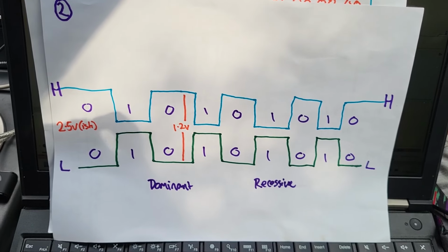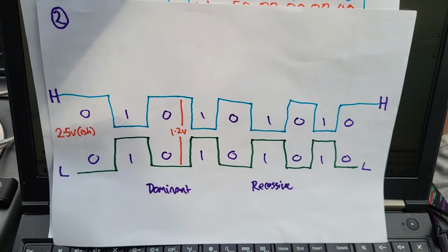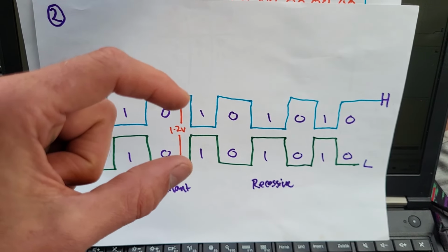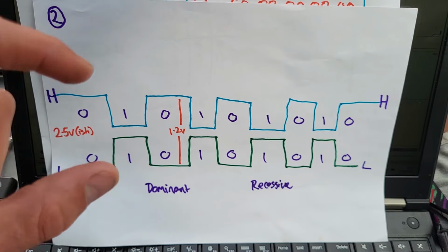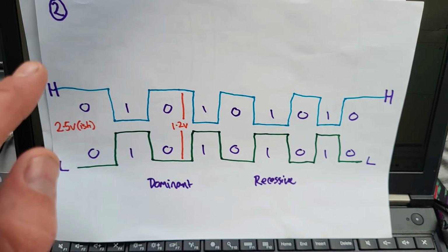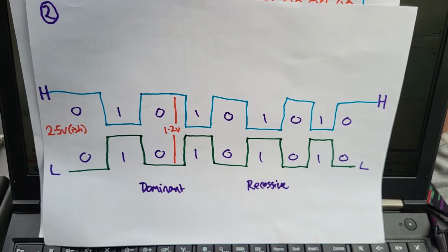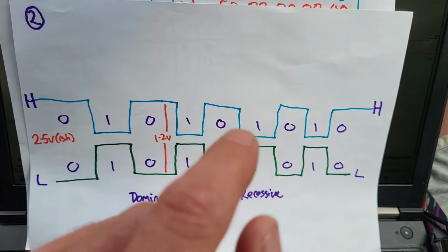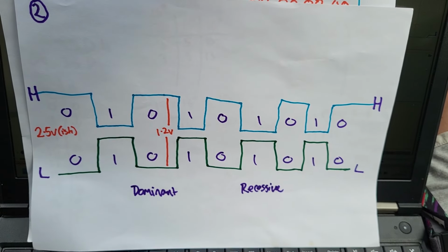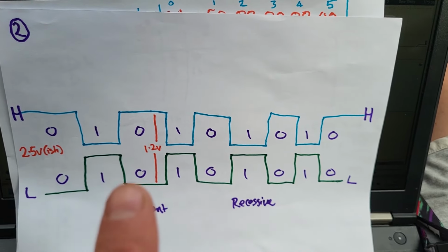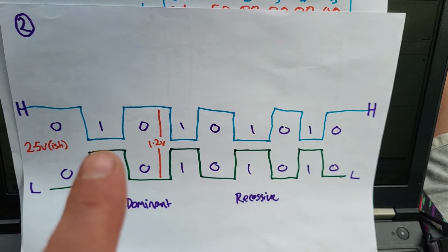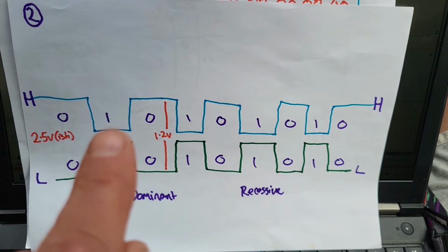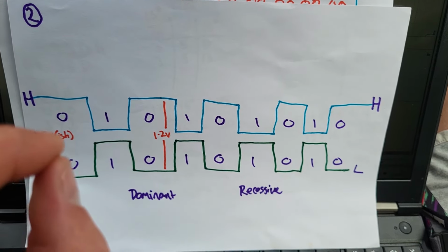Sorry, not sorry. Anyway, with high-speed CAN bus 2.0, the key thing is we're looking for a voltage difference of 1.2 volts between CAN low and CAN high. Our middle point is going to be roughly 2.5 volts. So the high edge of low might be, let's say, 2.49 volts, and the low edge of high might be 2.5. So very, very close to one another.